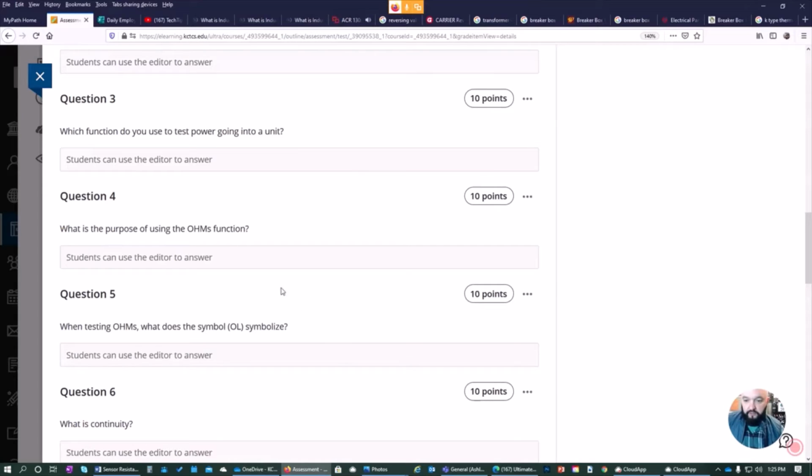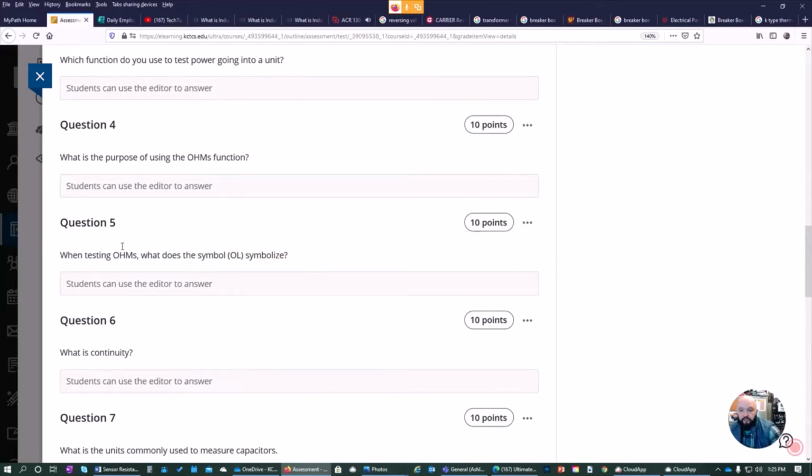Also, on a compressor, you have start, run, and common windings. They all should be closed together. That's one of the most common functions, to test the resistance in windings in all loads. Testing the resistance through a coil on a contactor or relay: if it's open, that's a bad contactor, that's a bad relay. It's not going to work.